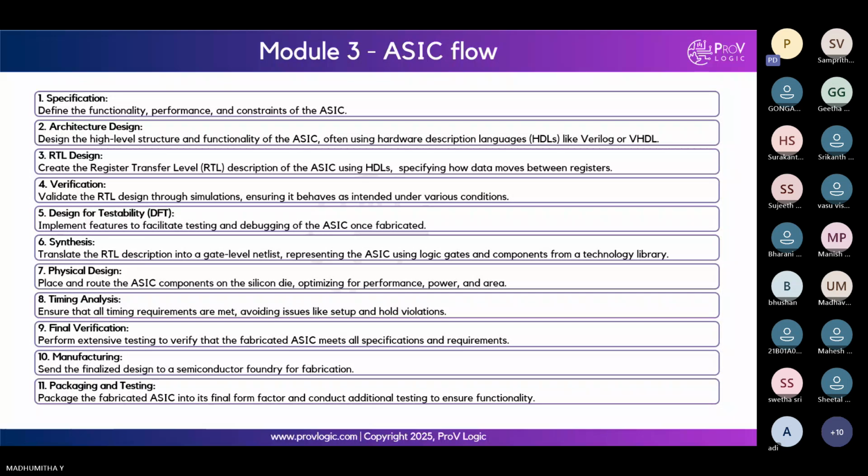Functionality must be maintained because we are going to deal with millions of transistors, and millions of operations are going to be handled by this particular IC. So if the tool which we are going to use for this physical design is going to alter the functionality, then there is no use, right? The entire design is completely faulty. So the first thing is functionality of the IC must be maintained. Second thing is optimization of PPA, which is power, performance, and area.